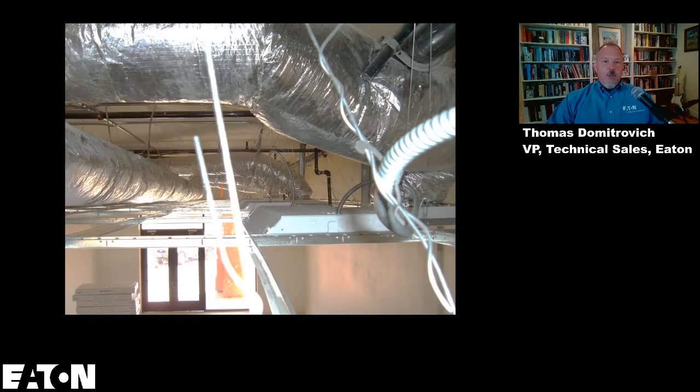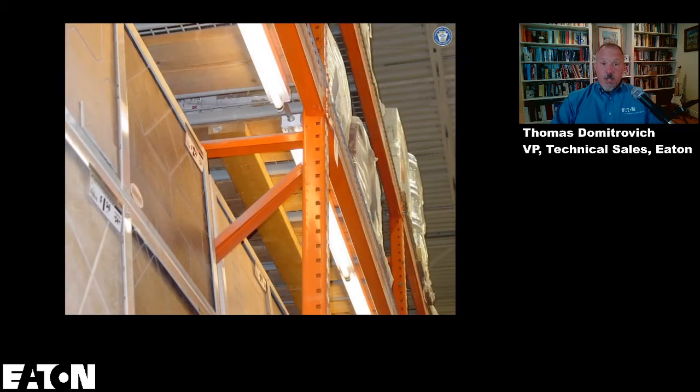So when you're looking at a lot of these types of applications, we like to use the body of that luminaire to run wires to the next light or possibly to something else, right? But if it's not listed that way, then you can't use it in that manner. So these types of lights, and I've done it myself, where you pull that wire and use it as a raceway to get to the other side, right, and provide protection.